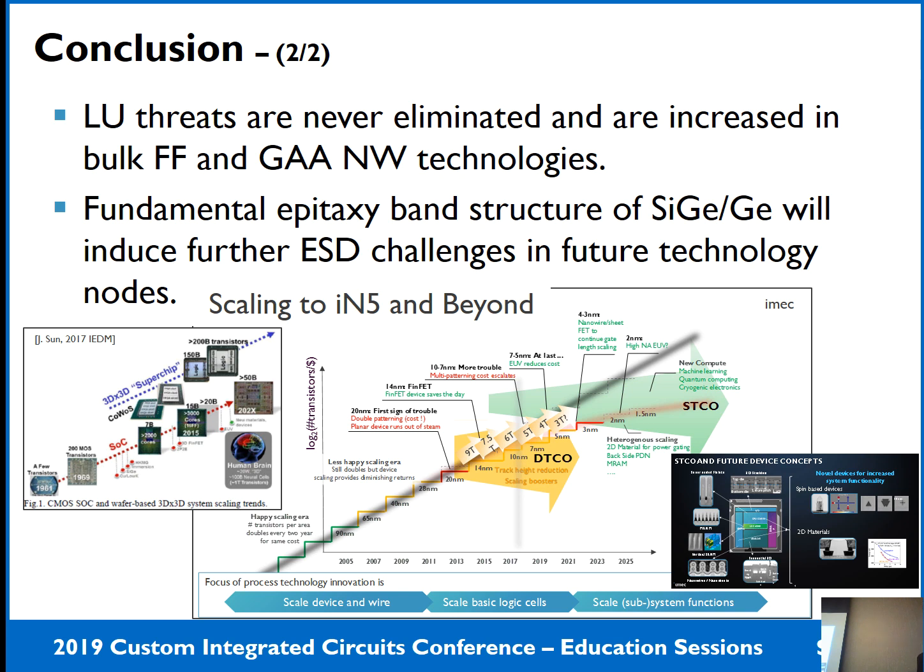So, open for questions? I have a quick question. Is the rotated STI diode also working for all-around kinds of structures? Yes, because this rotated STI diode is mainly used as an STI diode. So as long as you keep it, if you do not use the dielectric isolation, then this will also work for gate-all-around technology.